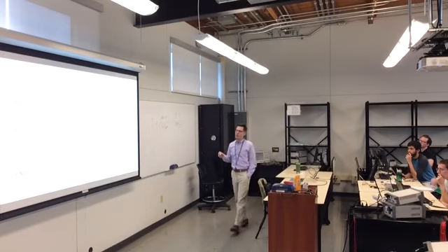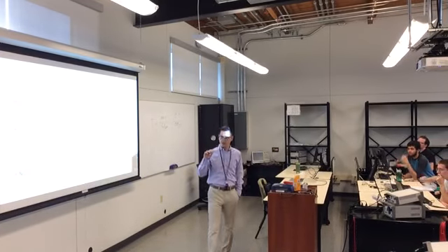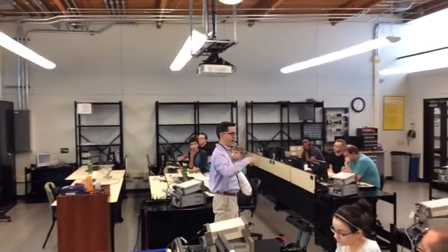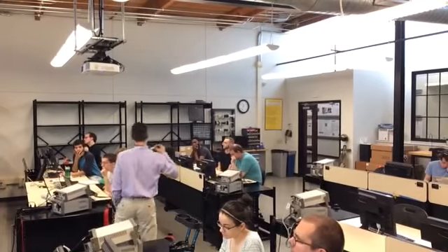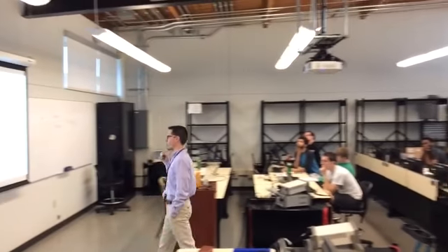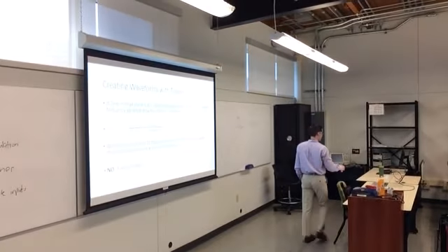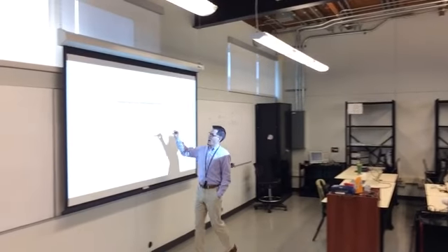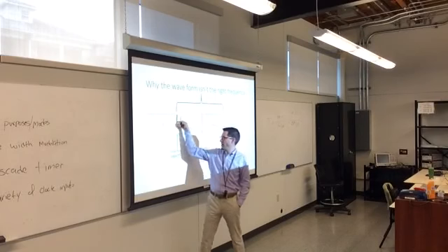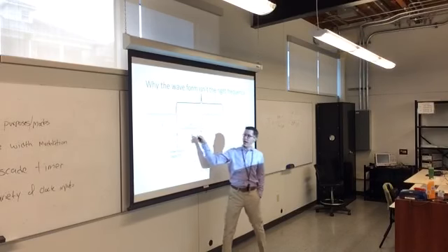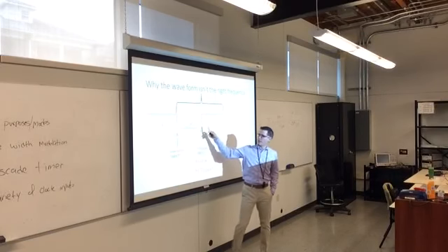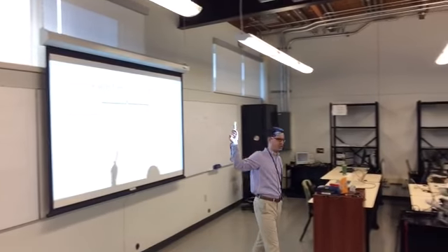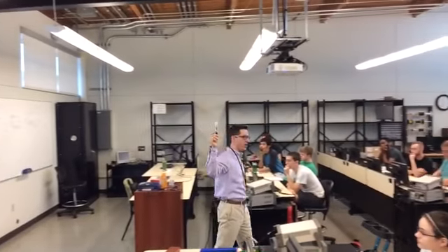Because if you wait for the timer to go up and then you toggle it, and then you wait for the timer to go up again and toggle it, you're going to be off by a factor of 2 in generating your square wave. Think about it this way. If I wait some period and I toggle my pin, and I wait some period and I toggle my pin, 2 time periods have gone past, so my frequency is actually cut in half. My frequency is not 1 over that simple period.